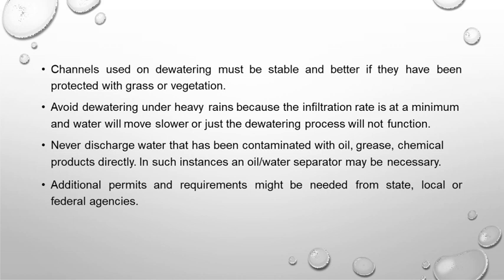First, the piston moves backward and forward in the cylinder due to the rotation of the crank. During the outward stroke, the piston moves to the right. This movement causes a vacuum in the cylinder, and the atmospheric pressure on the water surface forces the water into the cylinder through the suction pipe. This force of water opens the suction valve, which is a non-return valve. On the inward stroke, the pressure of water closes the suction valve and opens the delivery valve. In this stroke, water is forced up into the delivery pipe, and so water is raised to the required height or pressure.